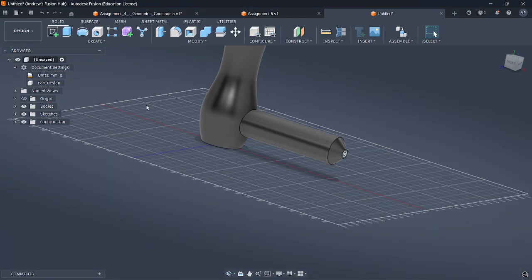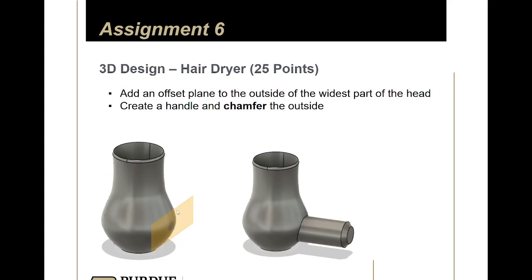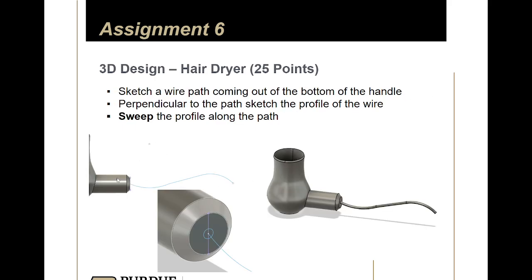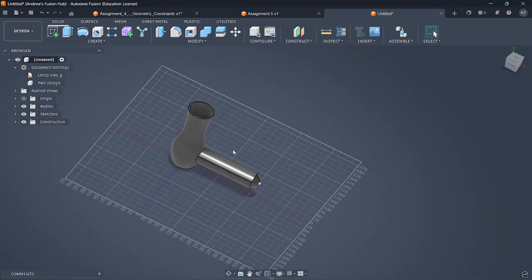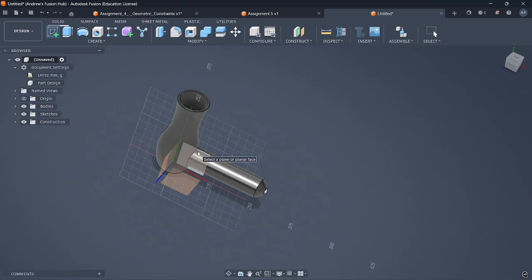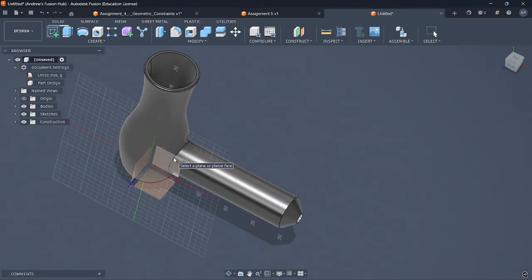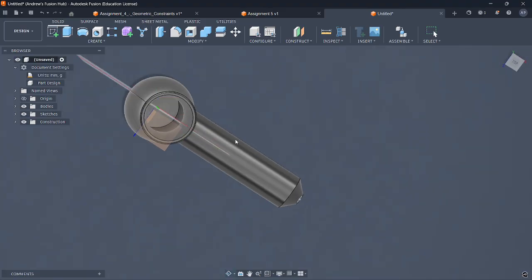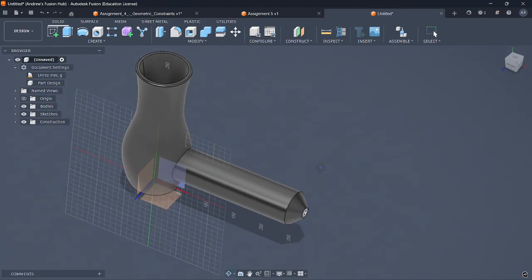And then I'm going to make another sketch which represents the path the wire is going to take. So I'm going to make a sketch. I'm going to choose this plane here, which is the front plane. And this is another reason why it's a good idea to base your sketches off the origin, just because it'll make a nice clean cut through certain things, right?